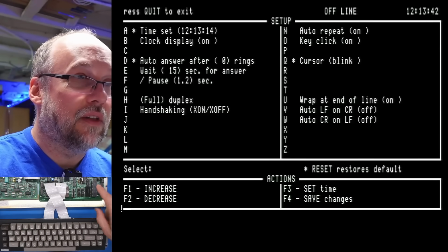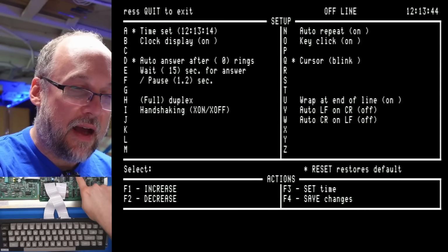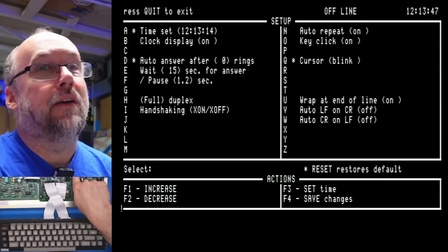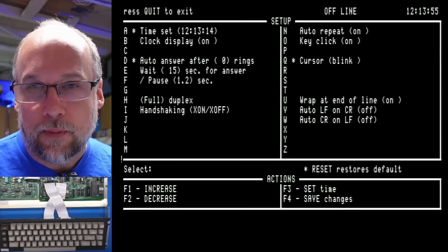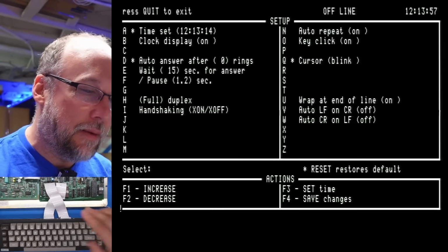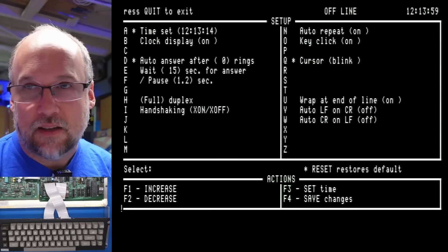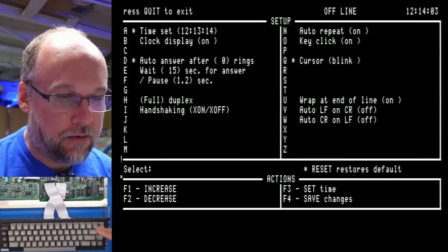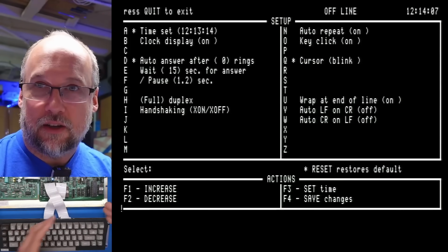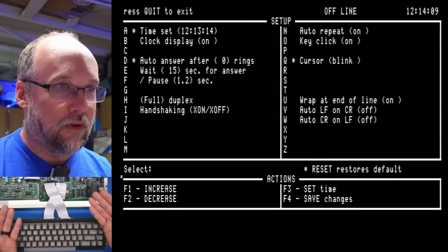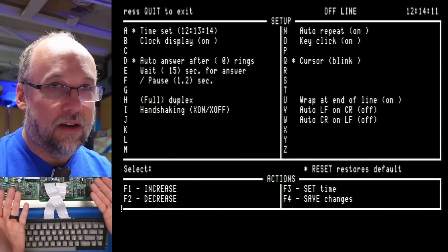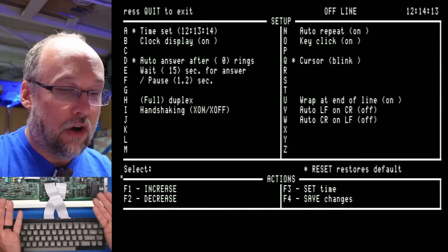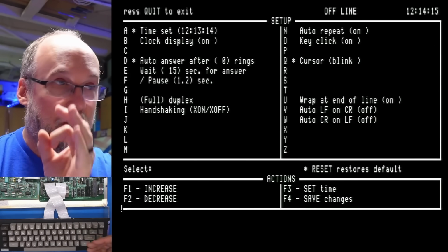I wonder if the little SRAM that's on this board is bad. It's not hot or anything. Now, also people had suggested that maybe one of the reasons why this wasn't powering up was because there was no battery in here, but that's not really normal for most battery powered things. They always work without the battery. And that's because it was a rechargeable battery. If you had this thing stored for a while, the battery would drain and die. And then if you plugged it in and it wouldn't work, how would you even recharge it? It's not like you could just replace a coin cell.